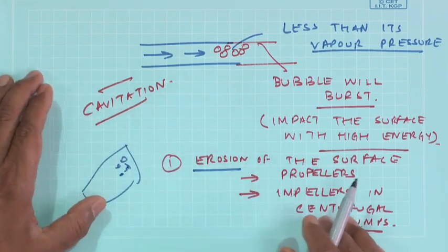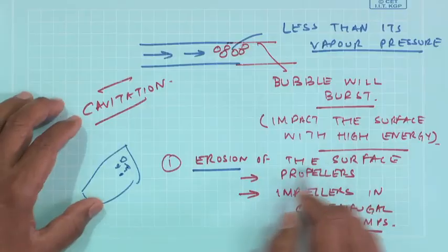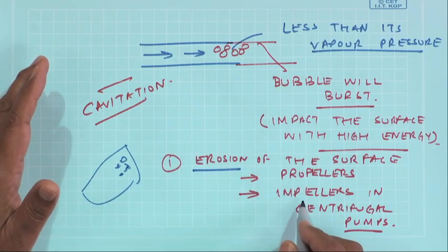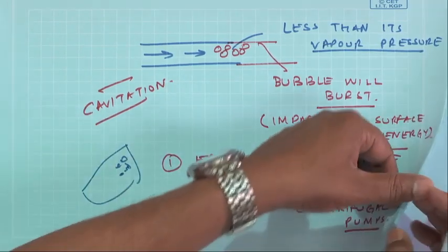So, cavitation is a physical phenomenon, we cannot avoid it, because if our process parameters are not under control. So, the way to reduce cavitation is to operate at low speeds. But how do you detect cavitation is what we need to know from a monitoring point of view.